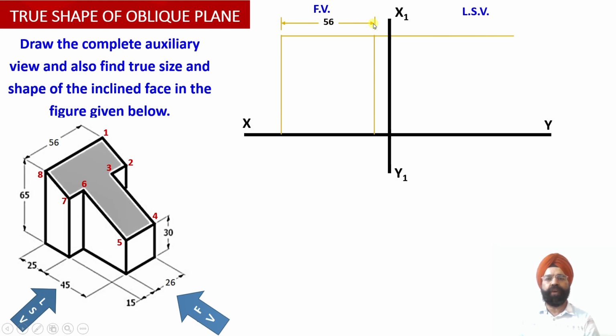So this is the width of the solid that we have drawn in the front view, and besides width we are going to require the height of the solid. The height of the solid happens to be 65 millimeter. So this is the height of the solid available from the isometric projection of this given solid. So we have drawn this height of the front view projection over here as 65 millimeter. This completes the outline for the front view projection which we have to draw over here.